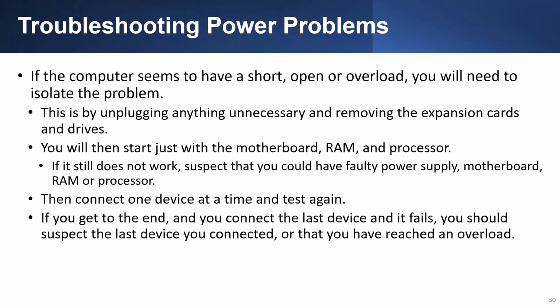Then connect one device at a time and test again. If you get to the end and you connect the last device and it fails, you should suspect that the last device you connected is faulty or that you have reached an overload.